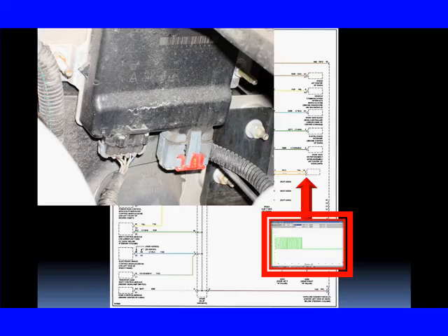We see if we can communicate with a TAC module. If we cannot communicate, now we're going to have to diagnose a communications failure. Question is, we can't communicate with anybody. Anybody on this bus can shut things down. All of these modules, if they go bad, can pull the module low, can talk all the time, or hold it high. Any of those things can cause a malfunction.